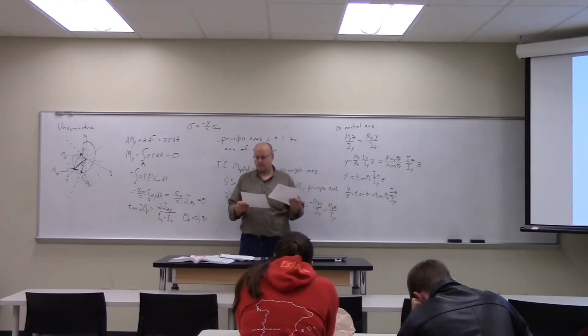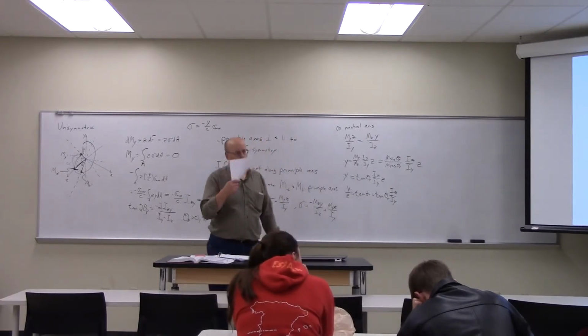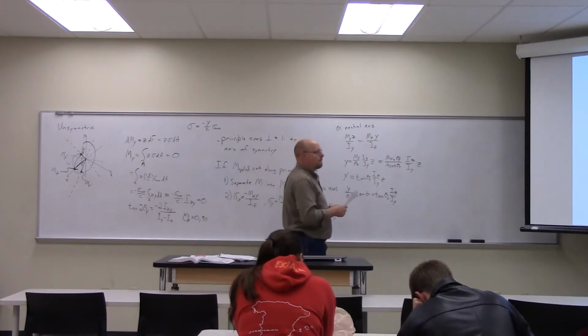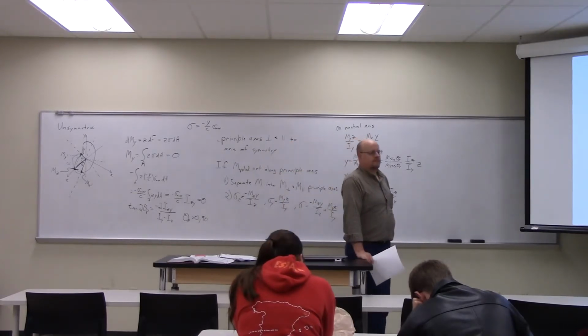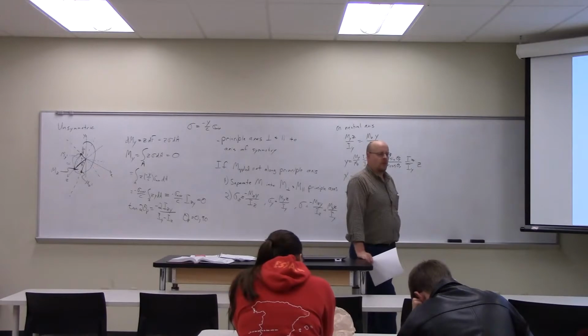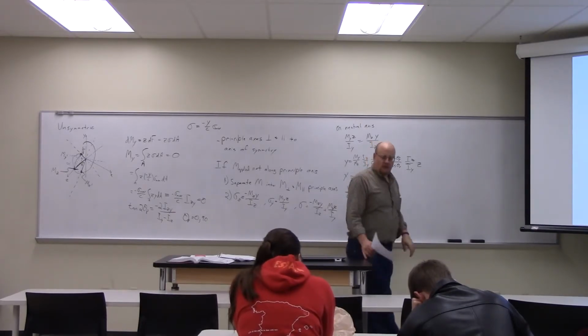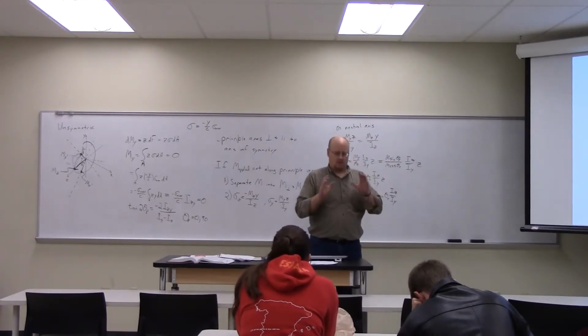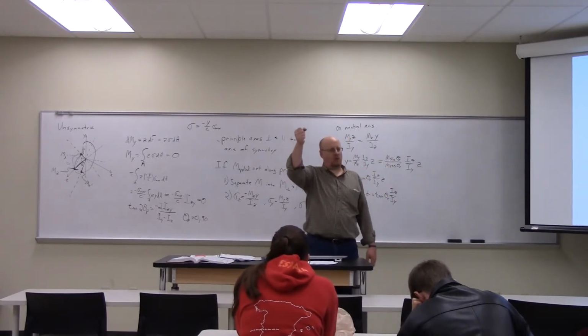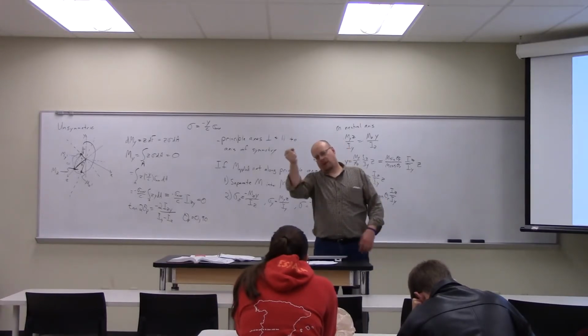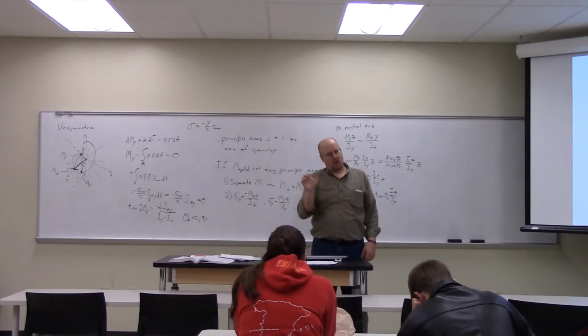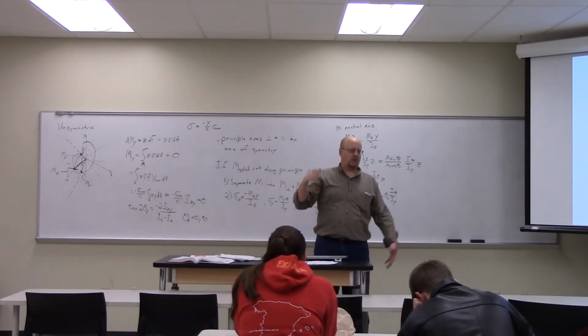You have a question? So we're not going to be dealing with a moment that involves three-dimensional rotation? You could, but you would define your system based on the applied moment. If I have a beam coming out of the wall, and I twist it in some random direction, I'm going to say that's my y-axis, so that I'm creating a z moment, and then I rotate it over to the new principal axis.